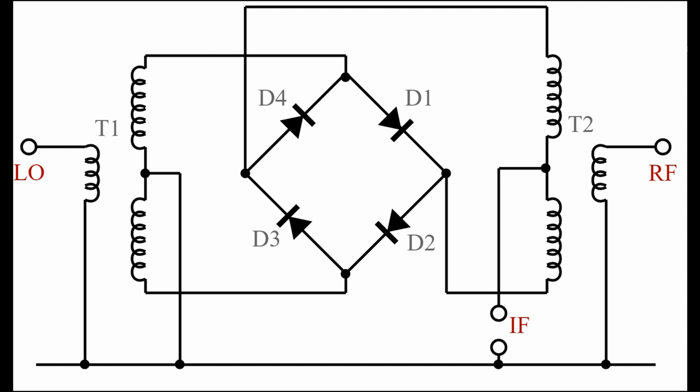We'll probably start with it, and once we get a working radio, we probably will add on and play with it, test, and try to improve upon it. But right now, the reason we're talking about our diode mixer is the first thing you need to build a diode mixer is matched diodes. We've got to get diodes that match.